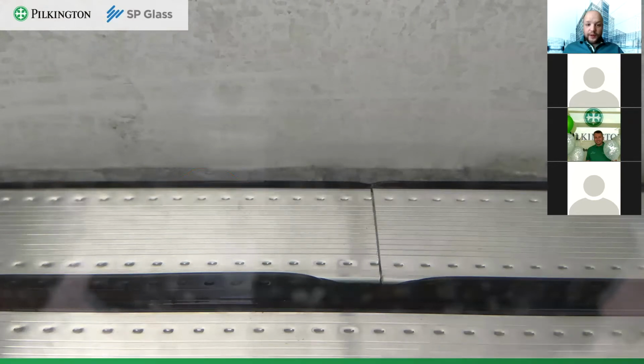For example, if you're having bent IG units, cylindrical bending, the IG unit is very stiff, meaning the glass has a cylindrical shape and cannot move. It cannot expand if the pressure rises, and it cannot really shrink if the pressure decreases under cold conditions. And that creates a lot of pressure in the butyl section. That is the one factor.